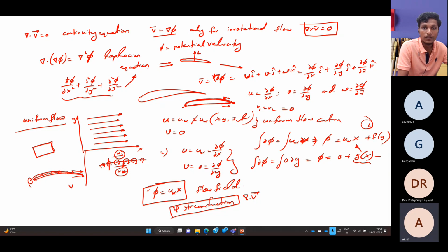From your understanding, did you find the two stagnation points on the flow over a cylinder? Yes, sir. So in the same way, you should be able to see one more stagnation point on the airfoil also. If that stagnation point is not at the trailing edge but somewhere here on the top surface or bottom surface, then the flow should take a turn completely around the trailing edge and come back to the stagnation point.